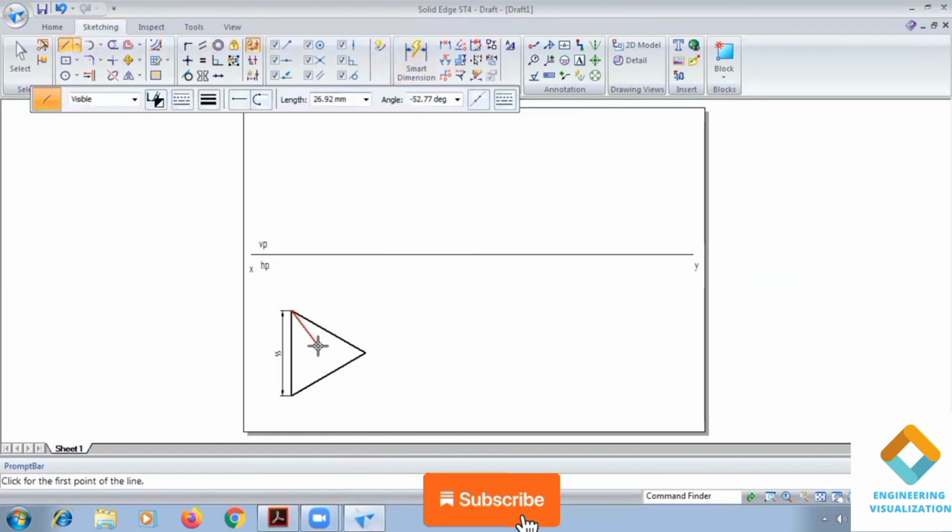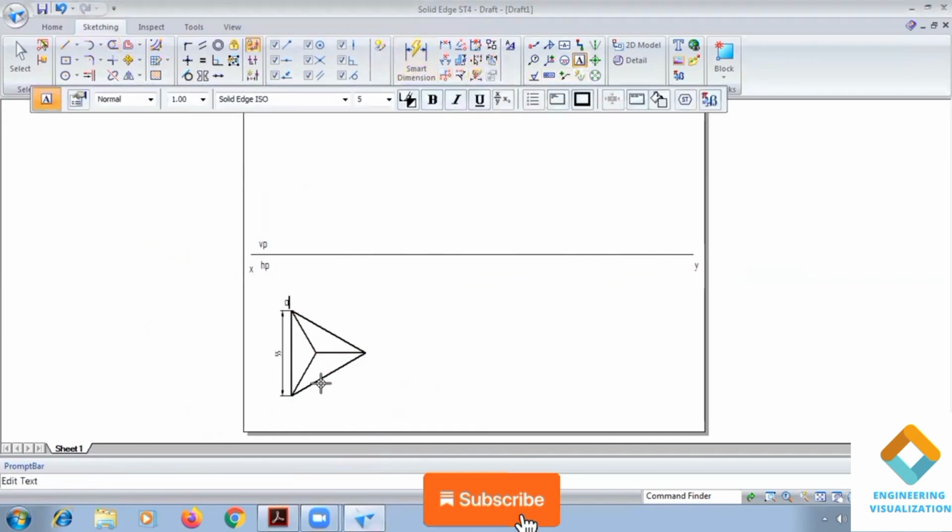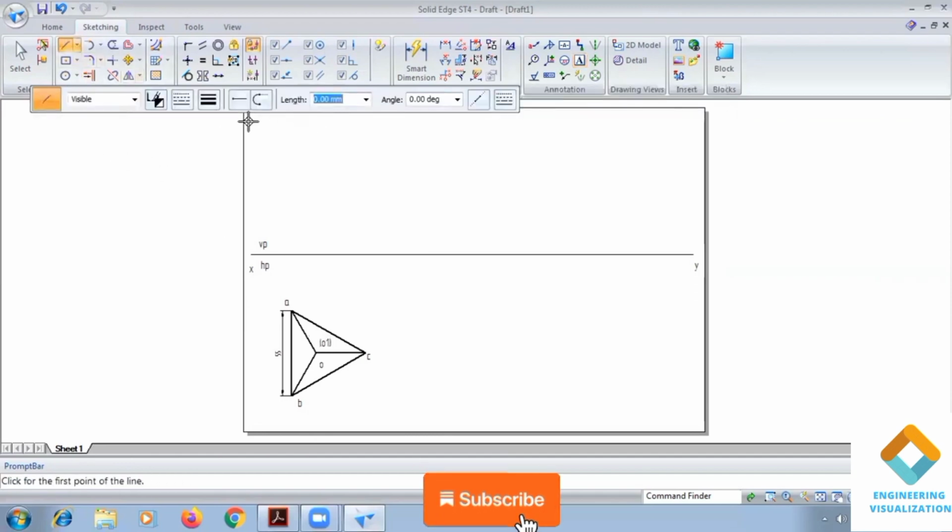Now draw the projection lines. Here we need to draw median lines. Two medians are enough to find the center, since it is a tetrahedron. It is one of the pyramids, so we need to draw all three slant edges. Now write the namings for it: A, B, C, and O1. Now draw the projection lines upward.